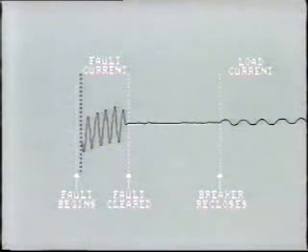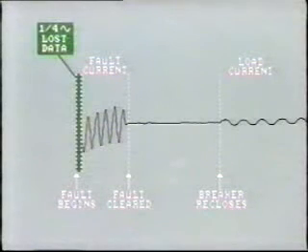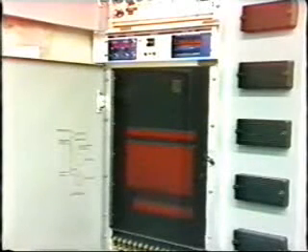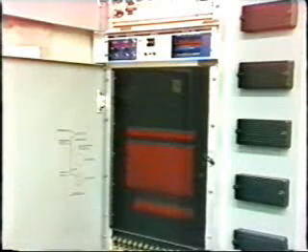Of course, this presents a problem since the data at the very beginning of the fault is lost. The loss amounts to about 1/4 cycle of data. Also, there is no way of capturing the conditions on the system just prior to the fault. In spite of these disadvantages, many users prefer the quick start system. They are willing to live with some data loss in exchange for the simplicity of the machines.